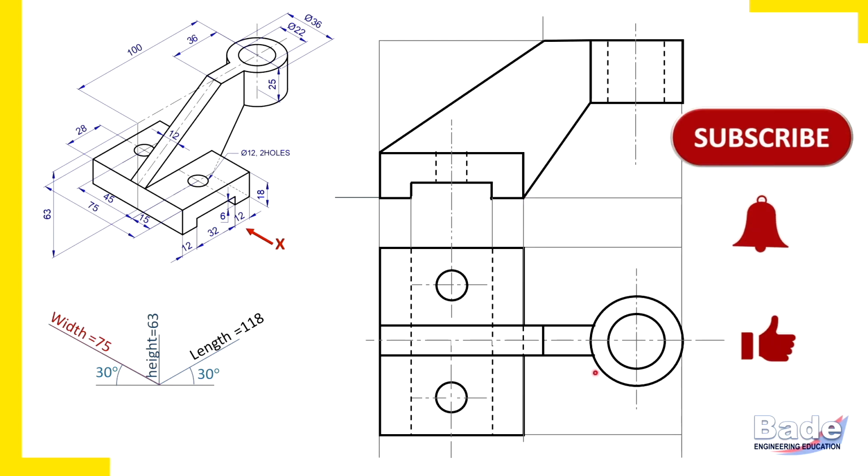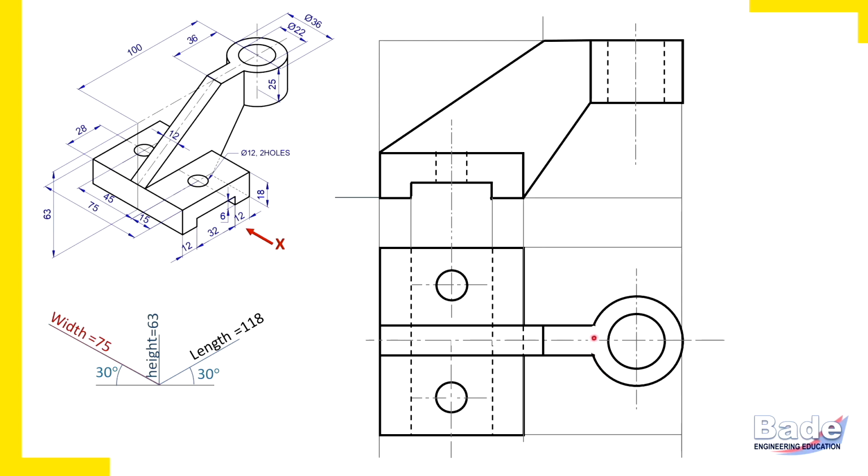Now here what? We should trim this portion, because these surfaces are in one single plane. That's okay. But one very important thing. A similar circular edge is at the base of the cylinder also. Here it is. And this circular edge is still there, but it is hidden from the top. So some portion of it will appear here. So don't forget to draw these hidden lines.